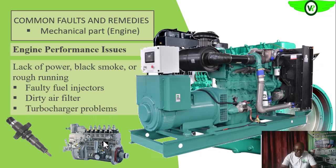So if that is the case, we need to clean up the filter as we said earlier, or replace the filter altogether. Or if we have turbocharger issues, okay, if it is losing compression, or we have oil coming from the, since we have the shaft that is connecting the turbine and the compressor section, that shaft needs to be lubricated because there is a bearing there.